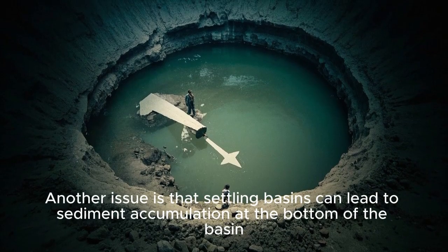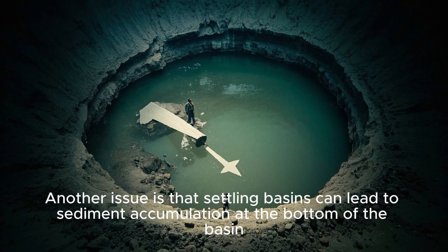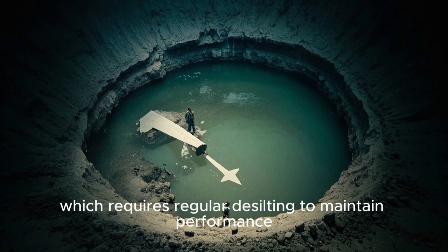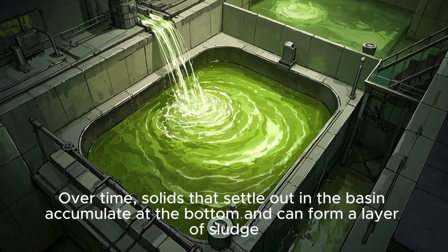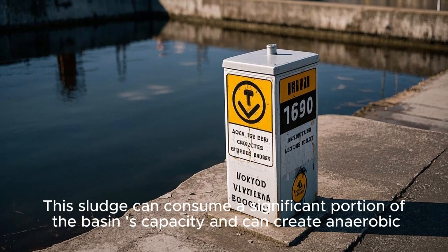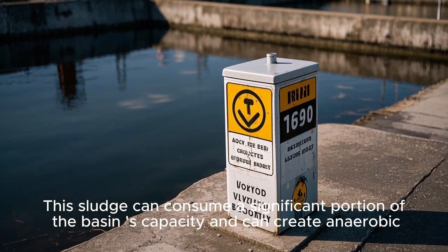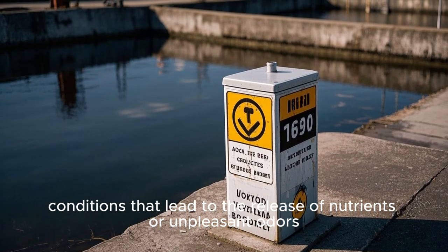Another issue is that settling basins can lead to sediment accumulation at the bottom of the basin, which requires regular desilting to maintain performance. Over time, solids that settle out in the basin accumulate at the bottom and can form a layer of sludge. This sludge can consume a significant portion of the basin's capacity and can create anaerobic conditions that lead to the release of nutrients or unpleasant odors.